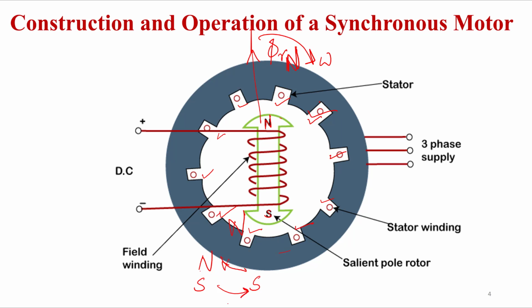So that means one time it will attract, another time it will repel back. Attract, repel back. That means it will just oscillate, it cannot start. Therefore your synchronous motor is not self-starting. It cannot start. So then what to do for starting?